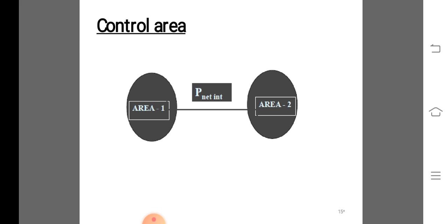Both loss of generation and loss of load can be simulated by imposing a positive or negative step input on the variable power load. A change of the set value of the system frequency F0 is not considered, as this is not meaningful in a real power system.